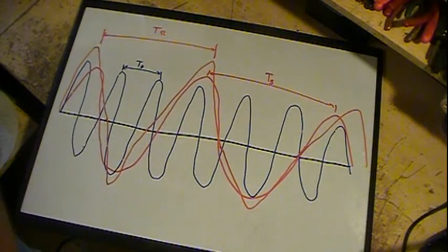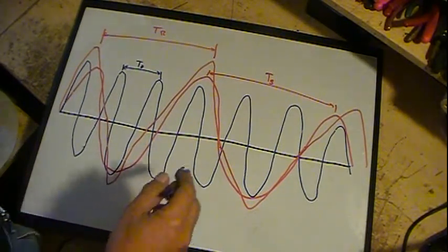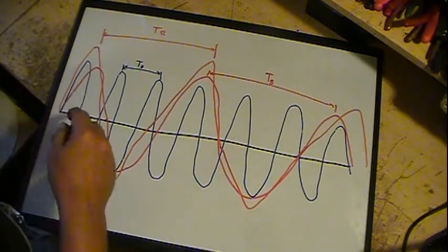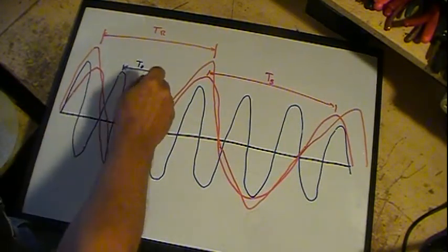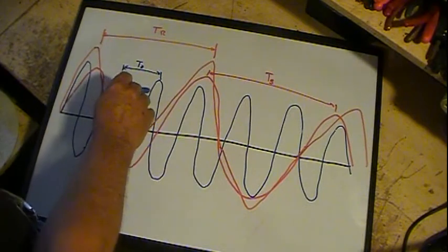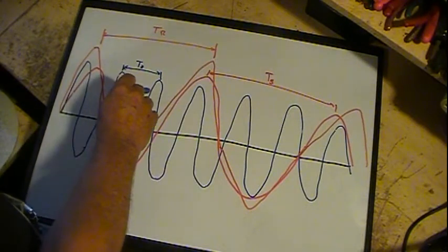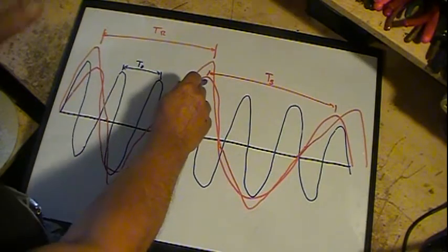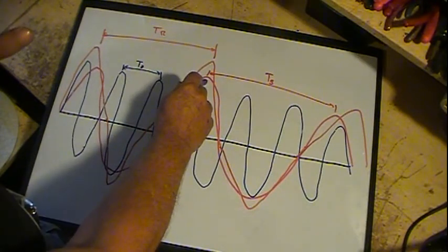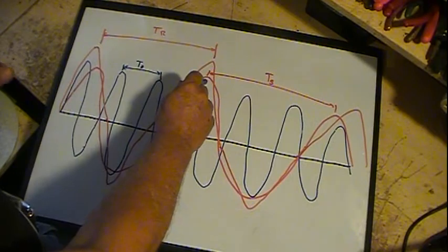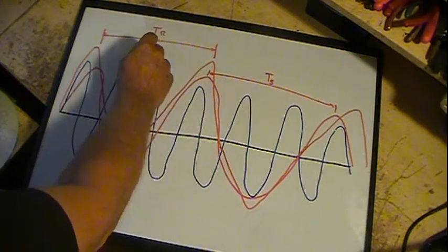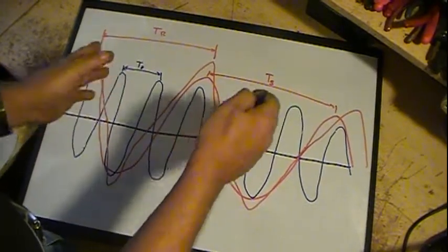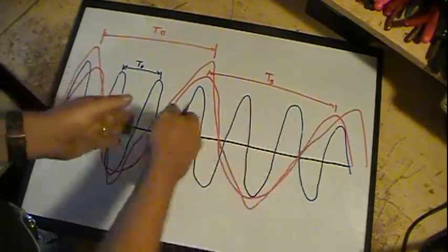Now realize what's coming out of that tube is this: your local oscillator frequency that has not been bothered at all will come out of the tube. Your signal will come out of the tube, not being bothered, nothing been added or subtracted from it. One resultant, which is the subtraction of them, and I didn't draw in the resultant. You can actually draw one in where they actually add together.